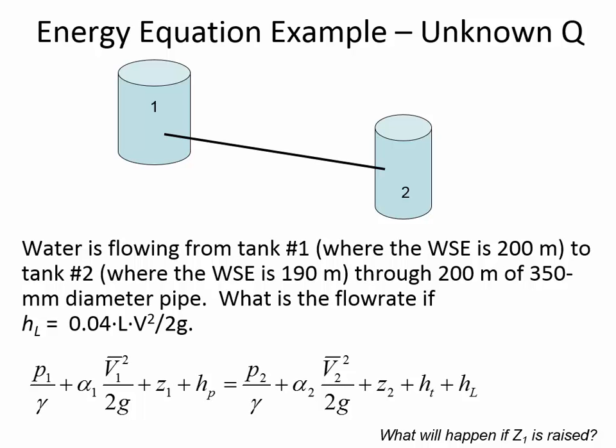How would it account for that? Well, it couldn't, because you'd have two different fluids, and what you could apply this for is from one fluid to the interface of the other one. In the same way that when we were doing the hydrostatic equation with different types of fluids, we had to do it in steps. Same kind of thing. We could just go from one interface to the next.